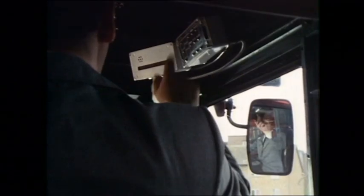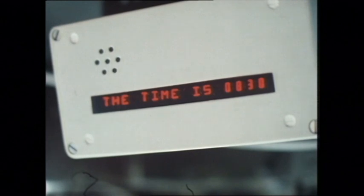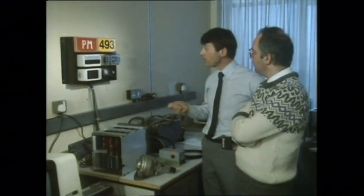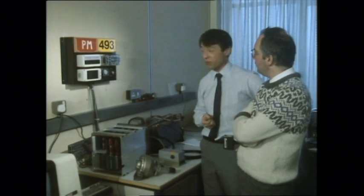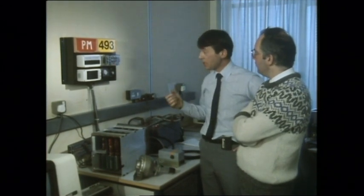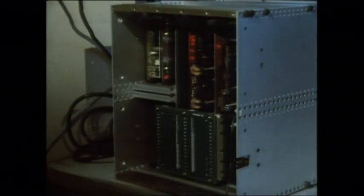Data coming to him is translated by the bus-borne computer to show him text messages which are available on the display, and he can respond to those messages saying okay, yes or no. And on some occasions the driver wants to make a normal voice call to the regulator. There may be some accident he's seen or what have you, so he can request a call by touching the call and the send button, and the landside computer will talk to this little computer and sort out which channel he can actually speak on.